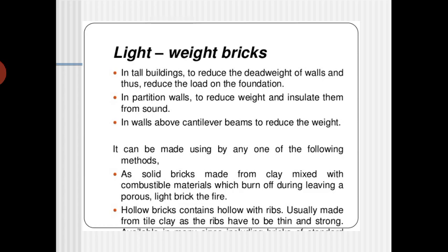So then lightweight bricks. So normally lightweight bricks are used in tall buildings to reduce the dead weight of the walls and thus to reduce the load on the foundations. Of course, the lightweight bricks are preferred in tall buildings. In partition walls to reduce the weight and insulate them from the sound, that also I will use it. In walls above the cantilever beams to reduce the weight. Wherever it is applicable, they will use it.